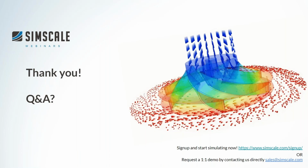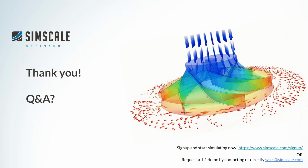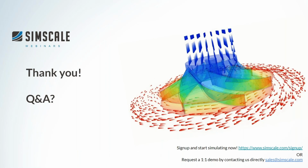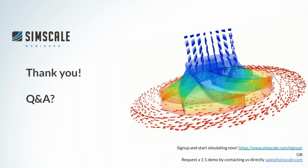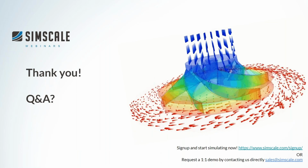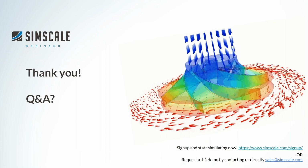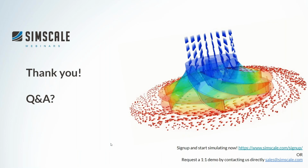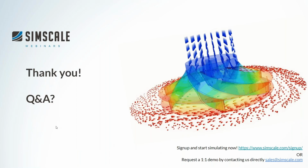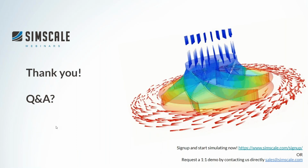The mesh size is very dependent on the actual pump design, since there's an automated Cartesian mesher occurring in the background for each setup for each geometry. Looking at just the baseline pump design, it was around 850,000 cells within the fluid domain. So that gives you a rough idea of what to expect, maybe a 10 to 15% variation up and down for all the geometries combined. In terms of the size of the pump, it depends on the direction, but around 7.5 centimeters roughly in terms of the fluid domain. But the overall assembly is probably larger. If Tony can add on that.